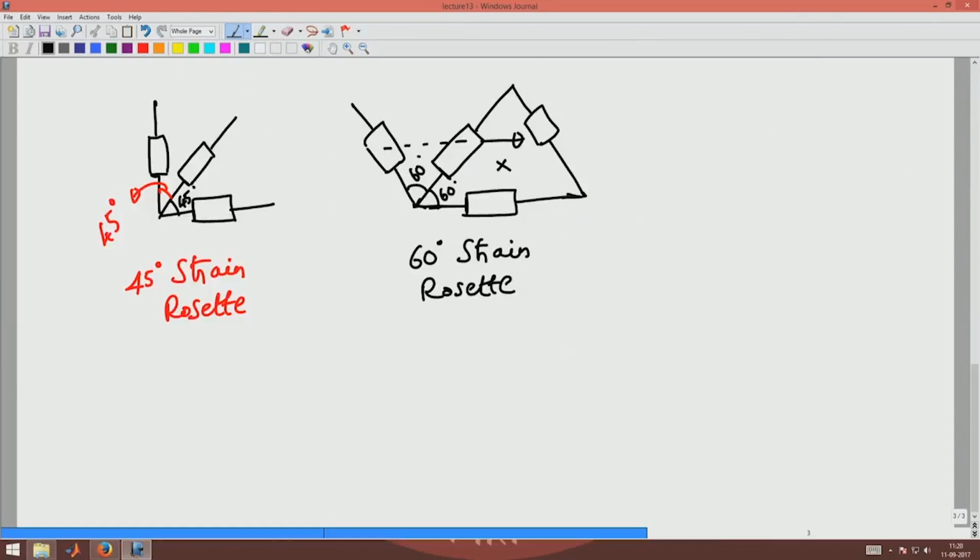So, the measurement point is that point. What you do is you measure changes in length, and from the changes in length you measure the changes in angle, and if you are going to follow this procedure to compute the strain, you will use what is called a strain Rosette to compute the in plane strain components.